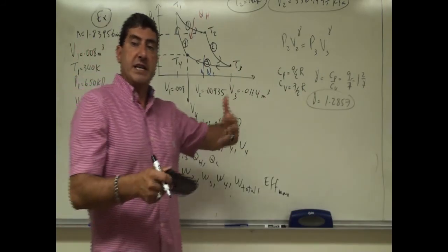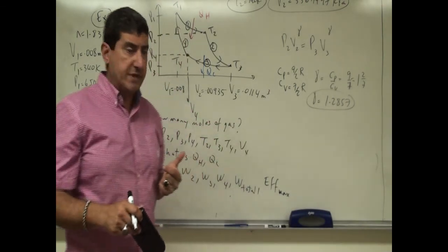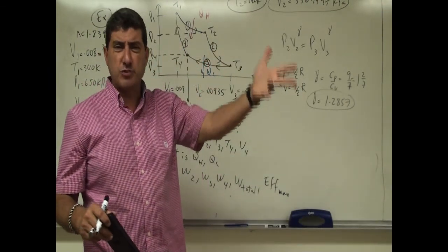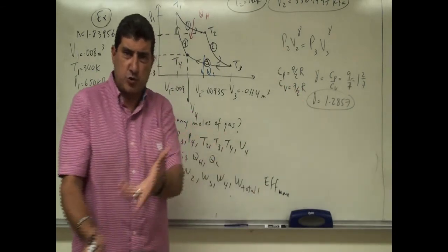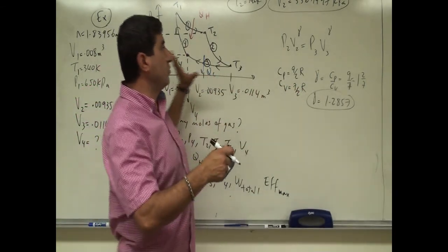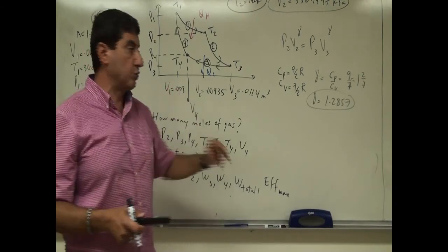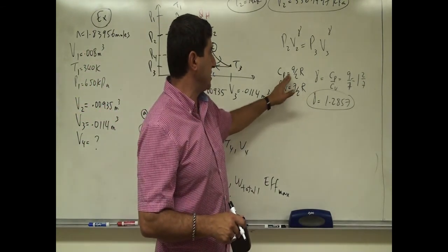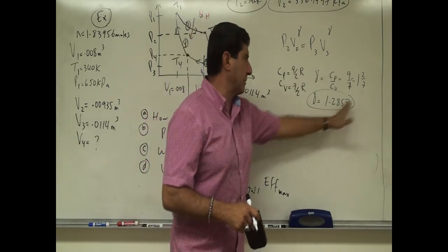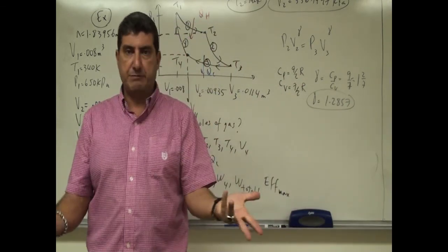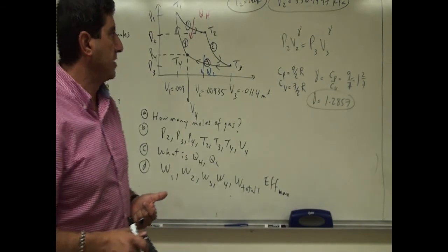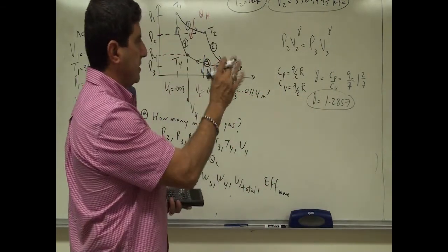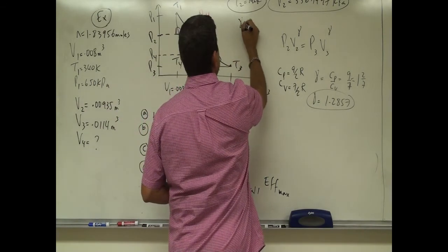The gamma might end up becoming, because of quantum mechanical reasons, slightly different, 1.29, 1.3, 1.26, 1.25. But in this case, nothing was given about the gamma, so we are assuming a regular Cv of 7/2 R, Cp 9/2 R, and so I'm going to use the gamma that you get by simply taking the ratio of those two, then you're going to end up getting 1.2857, right? So let's leave that over here, write that over here.